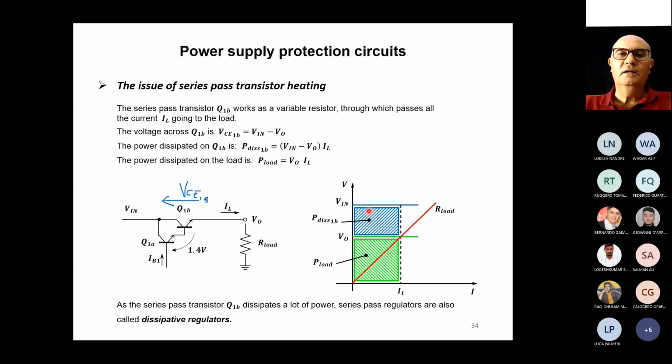So in absolute terms, the situation which is safer for the transistor is when no current is taken, when there is no load. If you consider an infinite load resistance, this infinite resistance corresponds to a vertical line. That means no current, and so there is no dissipation both in the transistor and in the load, which is different from the parallel configuration, if you remember.